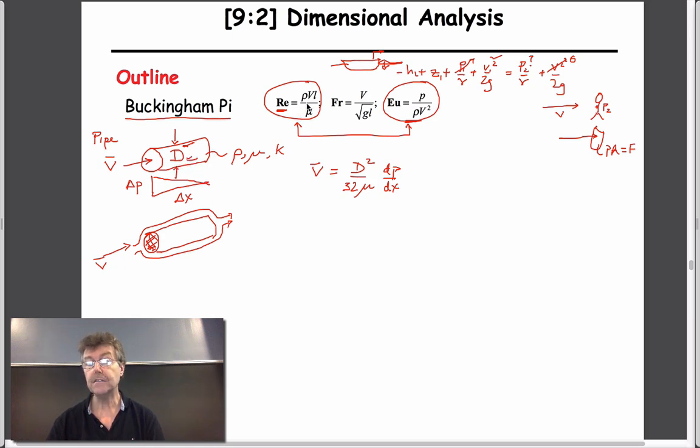This is our viscous effect in the Reynolds number. And in this particular case, the shear stresses are applied against, I guess, let me draw it on the outside of this pipe, but it's the same thing. One's inside and one's outside. So in all cases, we're really doing work against viscosity. In one case, the viscous flow is on the inside of the pipe, and the forces are therefore applied on that fluid inside the pipe. If it's an aircraft wing, which this would be a surrogate for, then the drag forces are on the skin of the structure. So internal flows, pipe flows, we'll spend 2 weeks dealing with those. External flows, we'll spend 1 week dealing with those, but really it's the same problem.